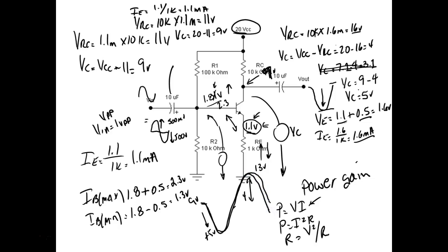So one feature of this amplifier, and we call it a common emitter amplifier, is your input and your output are 180 degrees out of phase. Now in audio, it doesn't make any difference because your speakers don't look at phase. Your speakers look at current, right? You understand that? So as long as we have the same number of phase shifts as we move through our amplifier, as long as your left and right channel are still in phase with each other, then we have no problem.